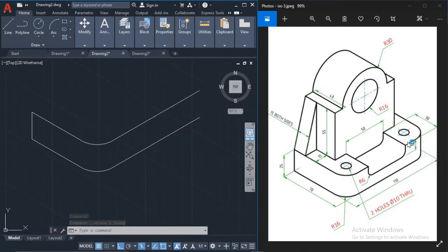So for the front, it says there's an indentation, and we come down by 12. This total distance is 110 millimeters. So if this is 110, and this is 50, 50 from 110 leaves 60, and the drawing is symmetrical. So that leaves 60, which would be 30 on this side and 30 on that side. That means from here to here is 30, and from here to over here is also 30.